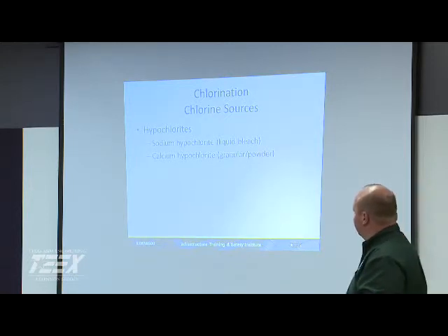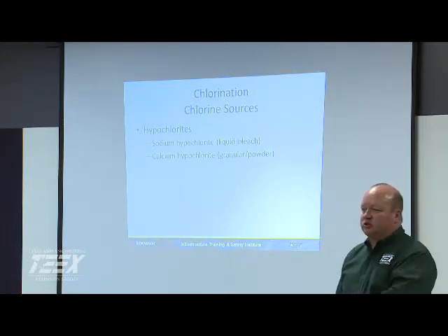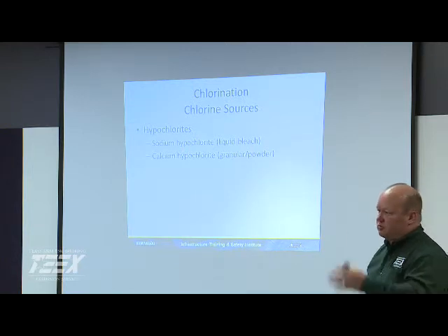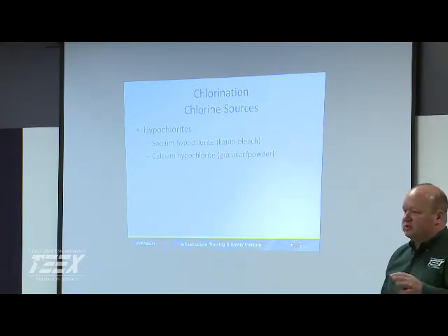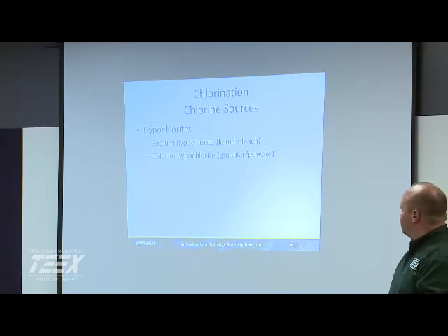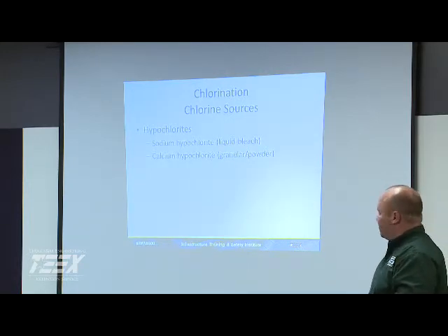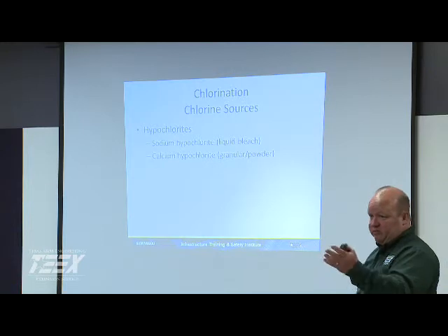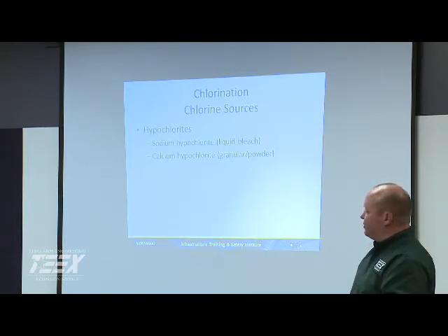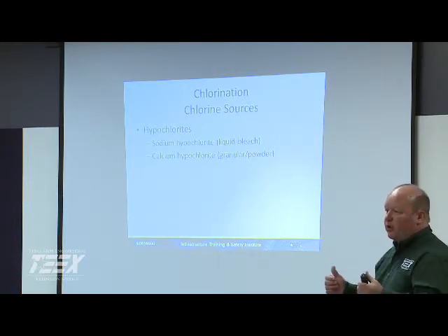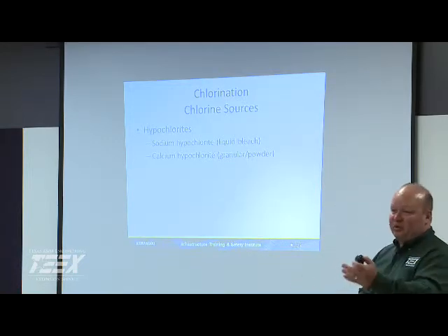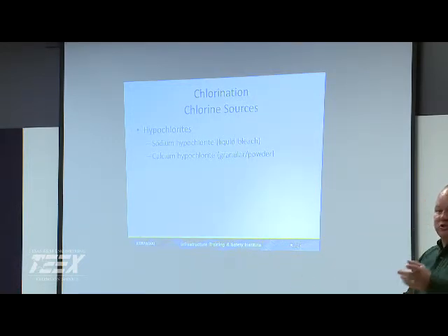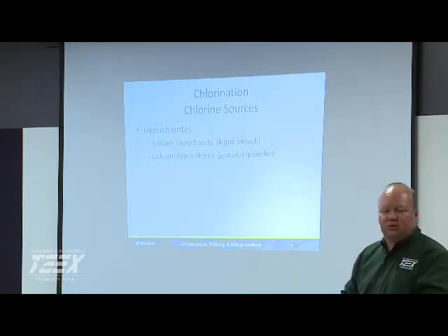So, hypochlorites, either sodium or calcium. The way I remember it, sodium chloride's on your table, bleach is in your house, so sodium goes together. Normally 6 to 12 or 14%. So it can take a whole lot to have that disinfectant power. Calcium hypochlorite typically about 65%. Chlorine gas 100%. So you can see where the benefit is depending on what y'all are pushing. What are y'all using out there, Robert?